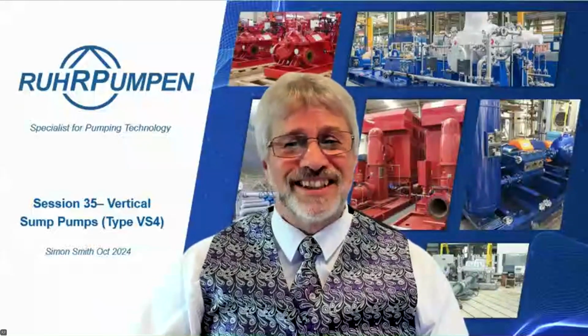Victor Mihangos says, what is the longest distance from the base plate to the impeller suction in each variation of the VSP pump? And do you build glass fiber material? Distance can be 20 foot is standard maximum. It can be longer. A bit more engineering required when it's longer than 20 foot. For a start, you need 2-piece shafts, for example. So it can be longer, but 20 feet is the standard maximum. And as for glass fiber, I don't believe we've built these pumps in glass fiber. I'm pretty sure we haven't done so, in fact.